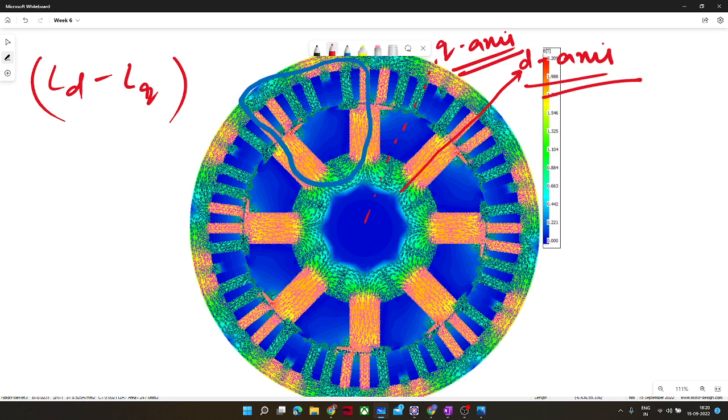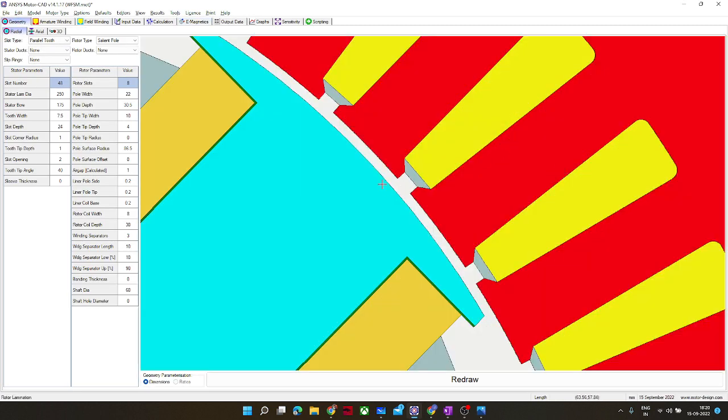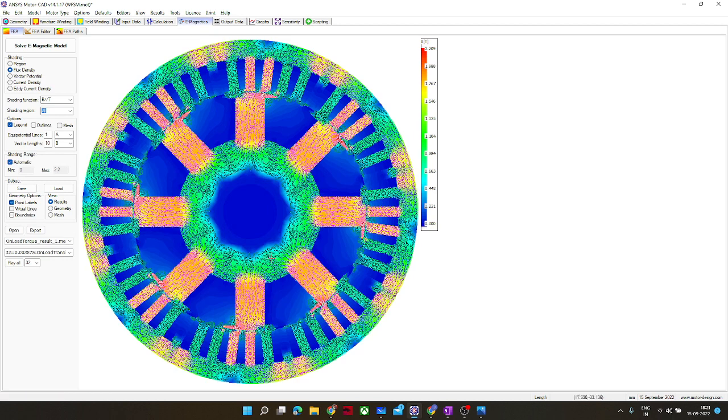And it is crossing this air gap. So this is the air gap. Let me show you. This air gap is very thin. If you see, the air gap would be around 0.4, 0.5 mm. Here it is 1 mm. Maximum it can go up to 1 mm, but generally people build with 0.5 mm, 0.8 mm. So 1 mm air gap is even considered a large air gap. So this was about it. Any question on this?